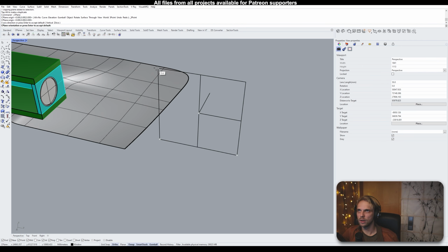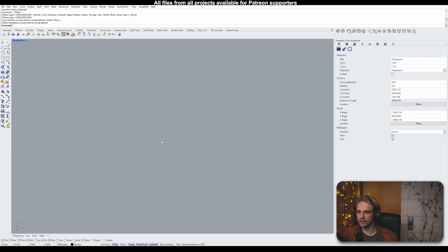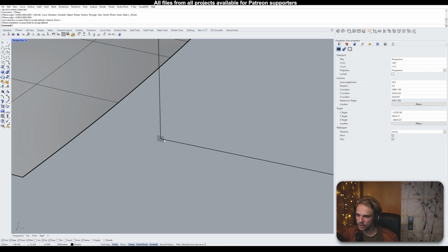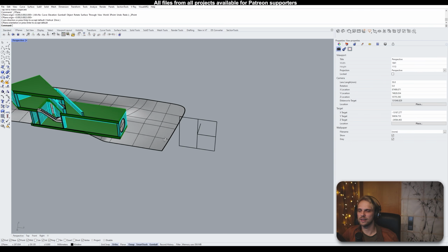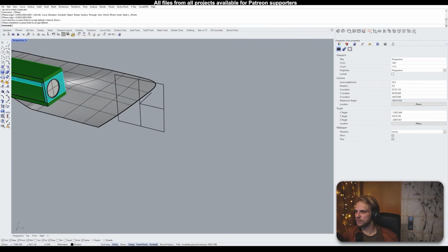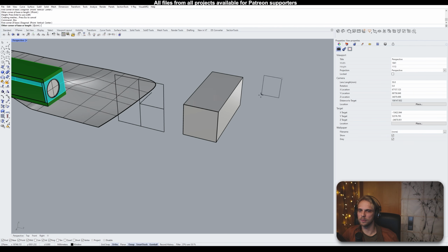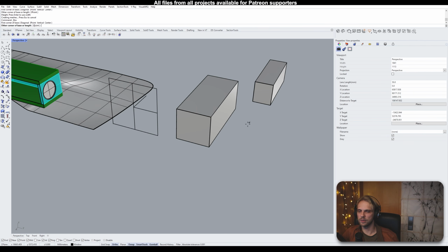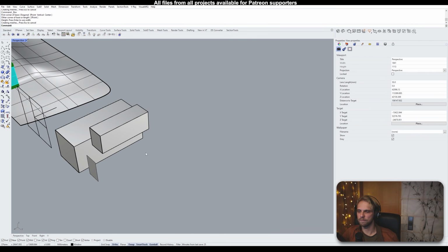Top left, you're defining the Y axis. So X, Y, it calculates the Z automatically, and you can see now there's a little grid here that basically says, okay, that's the new world. By the way, if you start creating boxes now, it actually creates them in this particular C-plane, right? So that's kind of neat.